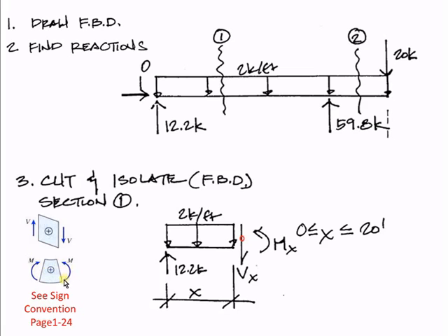So again, on the right-hand side, you're going to have a counterclockwise moment being applied. On the left-hand side, a clockwise moment being applied. Okay, so this is going to be consistent. So it's not just that we're choosing this to be positive, but also this is consistent with a positive shear, consistent with positive and negative loading as well, which is on the first page of your handout.